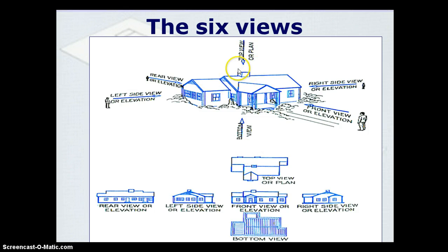The 6 views of, you can say, a residential block are shown. However, just see the visibility; these are drawn with the help of the third angle. This is the direction of the front view, and this projection is drawn here. This is the top view, how it looks is shown here. The bottom view is shown here. Also the left hand side view is drawn, the right hand side view is drawn, and also there is the rear view. So generally, based on the complexity of the object, we can draw the 6 views.